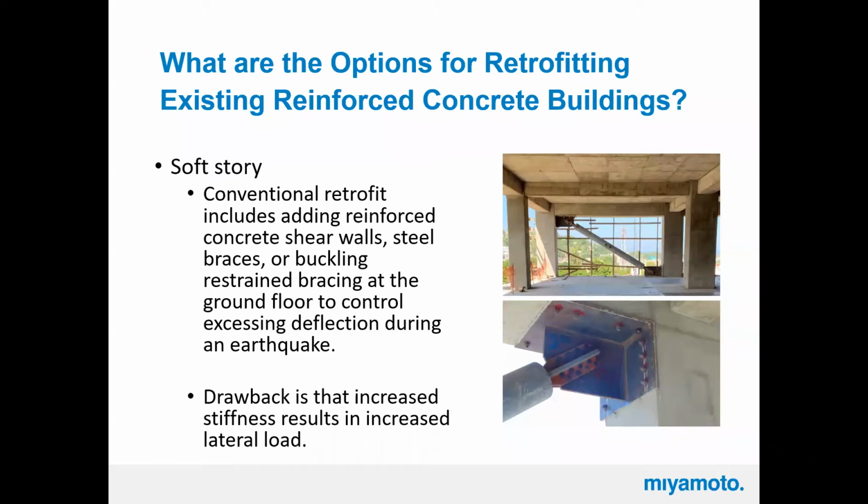Soft story, we've certainly done a lot of these. West Sacramento office is probably the leader in the world in doing interesting seismic retrofit projects. This one shows we're putting a BRB, a buckling restraint brace frame, bay into a building, and these things work really, really well, and they're very ductile. And they're also pretty predictable. So they do a really good job of controlling story drifts and protecting the rest of the building and the other elements that are in place already.